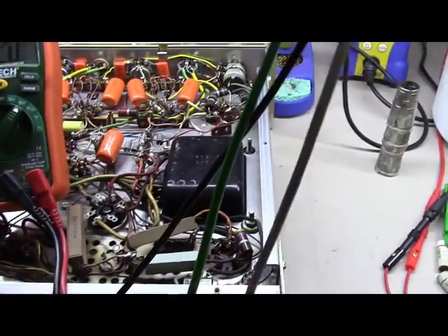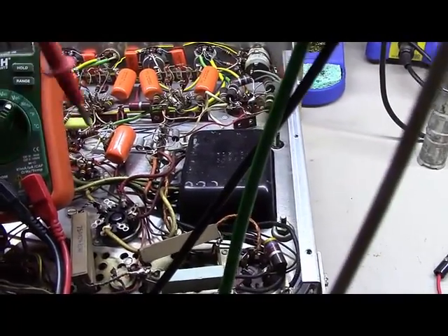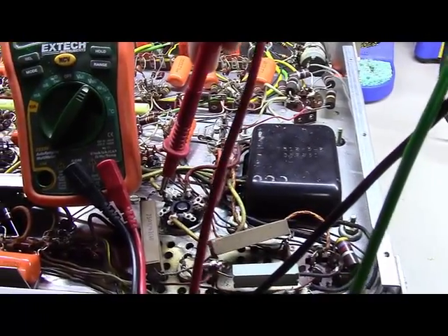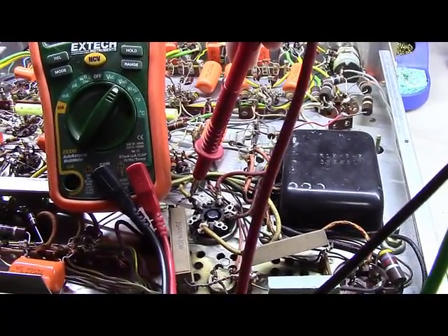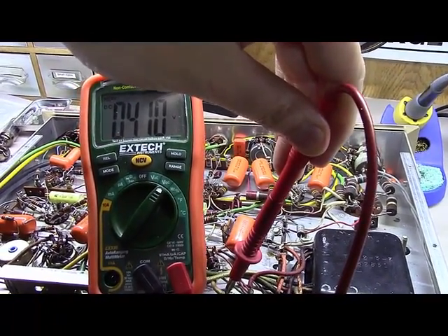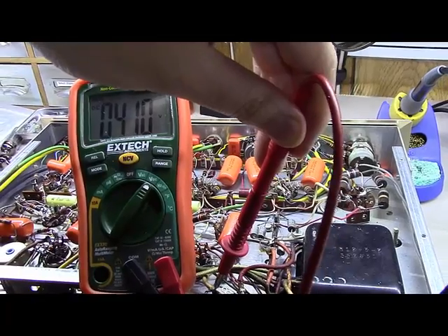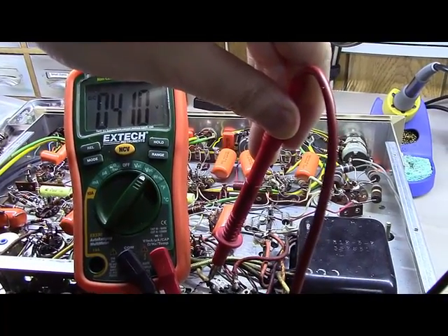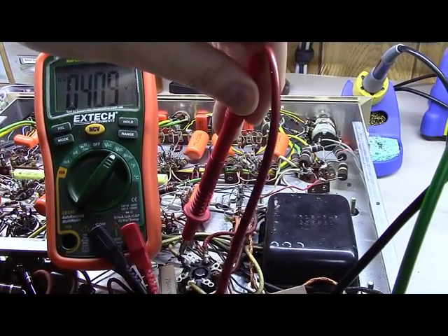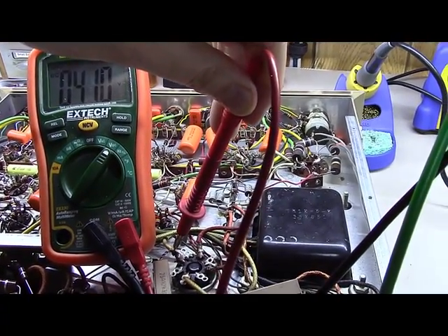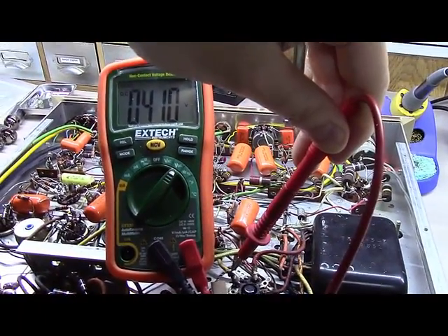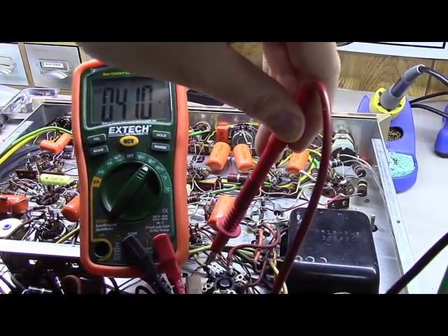So that first point coming off of that rectifier, if you'll remember, is actually this point right here coming off the rectifier. And if you'll notice, we have 410 volts. So the schematic said 430. We're actually getting 410. A lot of that has to do with the power being supplied by your line in your house. So mine might not be quite 120 volts coming in, causing me to have a little less here, but that's okay.